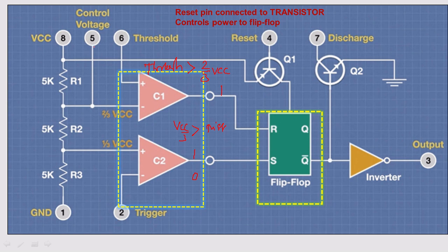Right. So you can see here the fifth pin is named as a control voltage. By using these resistors, I can determine a timing interval. Another reason why this control voltage is connected is that I can modulate. By enabling this control voltage, I can modulate the timing interval, so I can vary the time electronically by applying the modulation voltage to the control voltage input terminal.